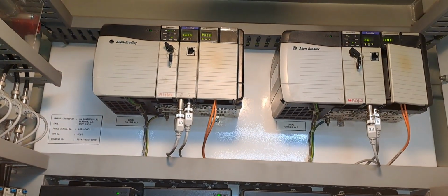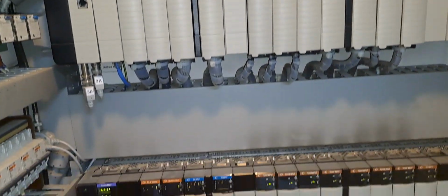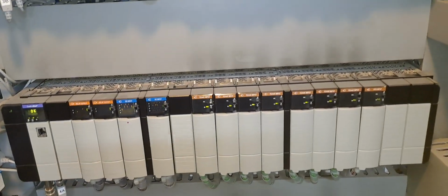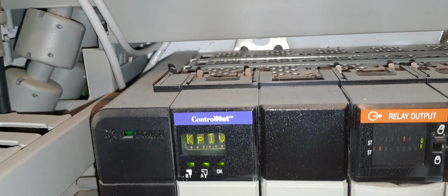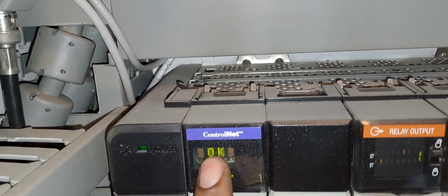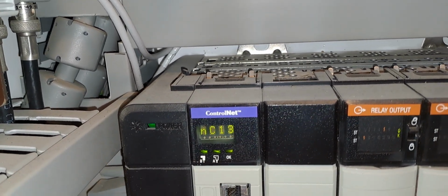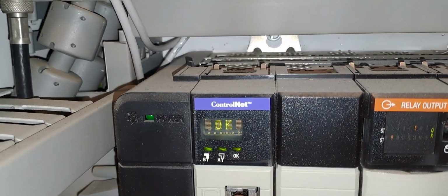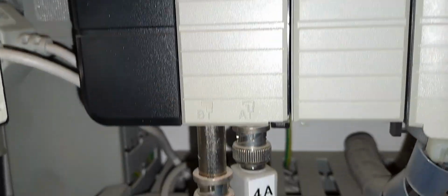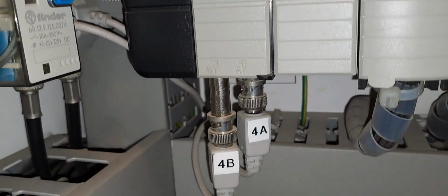So from the PLC, then the power supply, then this first rack. After this there is one more rack, the second rack. Here also all the field instruments are connected. In the same way there is a ControlNet card. The ControlNet card is reading all the field devices and giving commands to all the cards. It is reading from and writing to the field instruments. Actually this card is communicating to the PLC and giving all the status of this rack to the PLC. You can see in the same way there are 2 coaxial cables. These 2 coaxial cables are connected to the CPU.